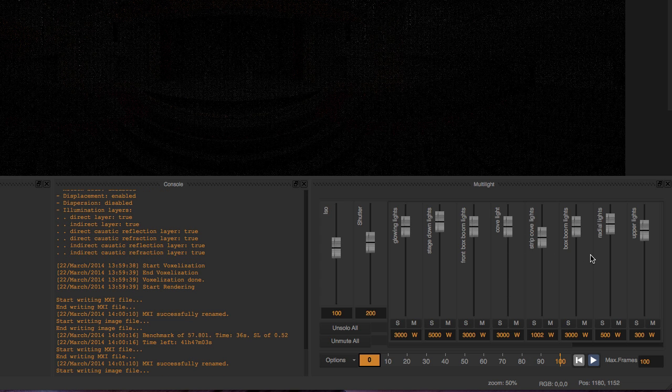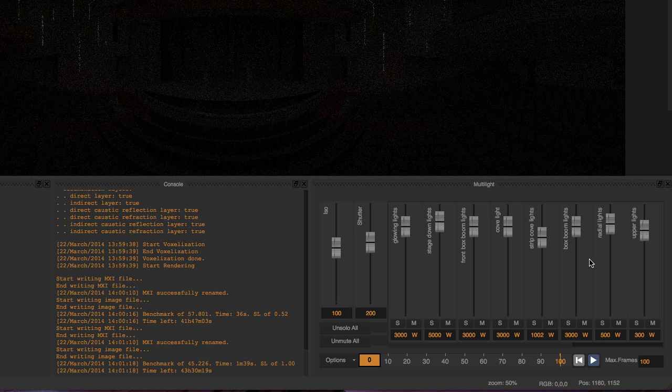And one of the options in Form Z was lighting intensity plus color. And so if I had chosen that, I would actually have a color chip down here as well. Those files are much larger because it's actually rendering color and intensity data into each light, and that takes up a lot more headroom. In this case, I just did intensity because I'm fine with the color of the lights that I pass through the materials in Form Z itself. And all I really want to do is control the overall intensity of each one of my sets of lights.